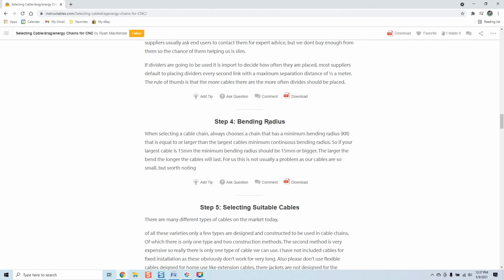Here we start talking about bending radius, and this is going to come in as we go all the way through this, because like I said, this is a different video, and I really hope everybody watches it to the end. When selecting a cable chain, always choose a chain that has a minimum bend radius that is equal to or larger than the largest cable minimum continuous bending radius. So if your largest cable is 15 mil, the minimum bending radius should be 15 millimeter or bigger.